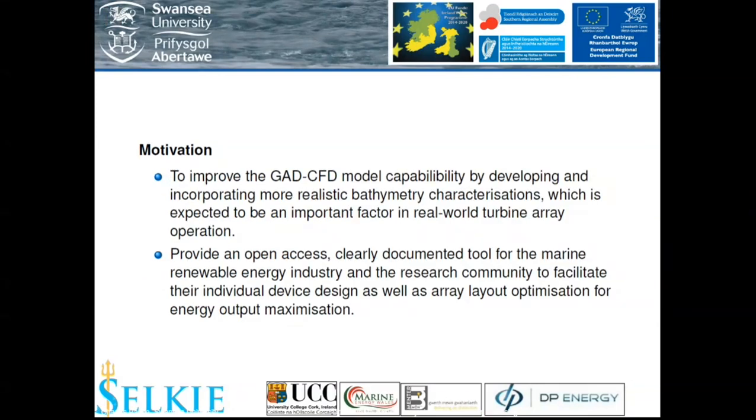We have developed a new generalized actuator disc CFD model, GAD-CFD for short, that achieves the required accuracy for simulating horizontal axis tidal turbines and their wakes. This new method combines a finite volume CFD code with additional source terms representing the rotors, including correct consideration of losses along the foil by modification of the distribution of downwash, recognition that foil cross-section varies along the length, dynamically changing Reynolds numbers, and the application of a tip loss radius correction.